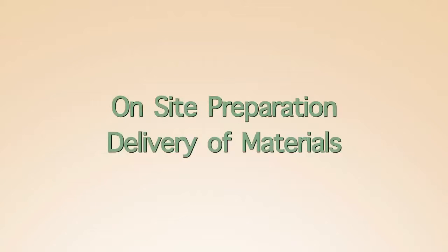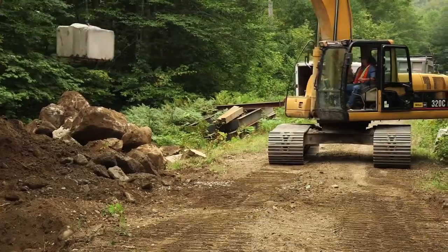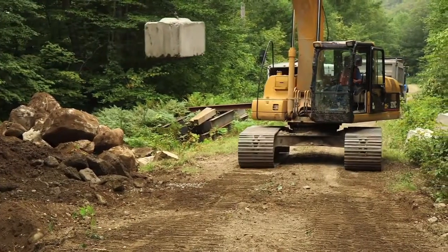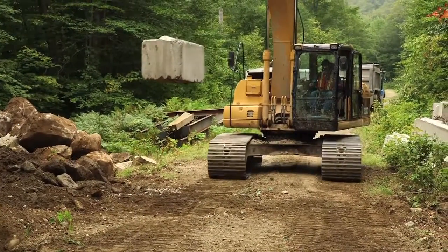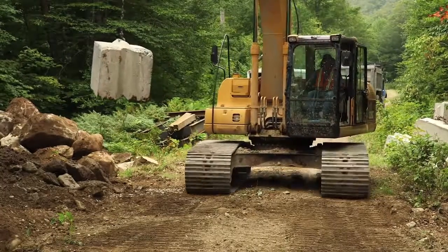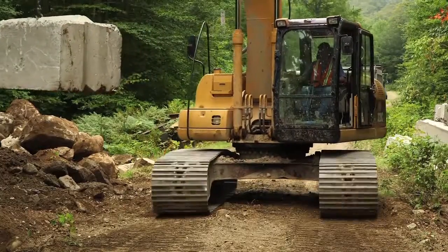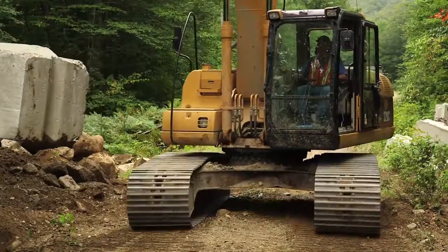On-site preparation prior to construction, delivery of materials. Prior to construction, as many materials and equipment needed for the bridge construction should be brought to the site in order to minimize the time actual construction takes. This is important in order to minimize the time the road has to be closed and can be critical if there are higher stream flows and water control is more challenging.